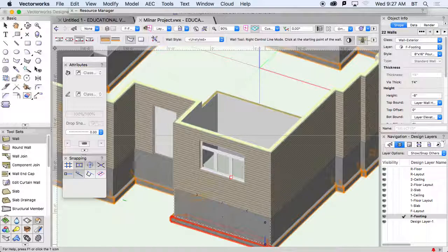How did it go under your foundation? Because I did a negative wall height. So I did -8, so it's going to go -8 down. Oh, I thought you did -4 feet for the foundation. Yes, so the elevation of the foundation is -4 feet. Then the wall height is 4 feet.